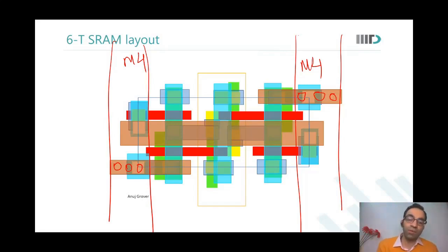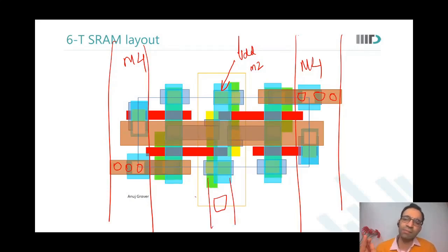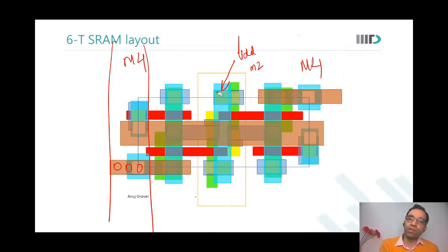Similarly, over here, the VDD supply is provided in metal 2. Are you able to see this? If you run metal 2 through the entire array, the VDD supply may see some resistance. To avoid that, you may also want to strap the VDD supply, provide a metal 3 stub and a metal 4 connection somewhere at some interval, not every cell, but somewhere. So when you design the memory array, you have to take care of the power routing of the memory array also very carefully.